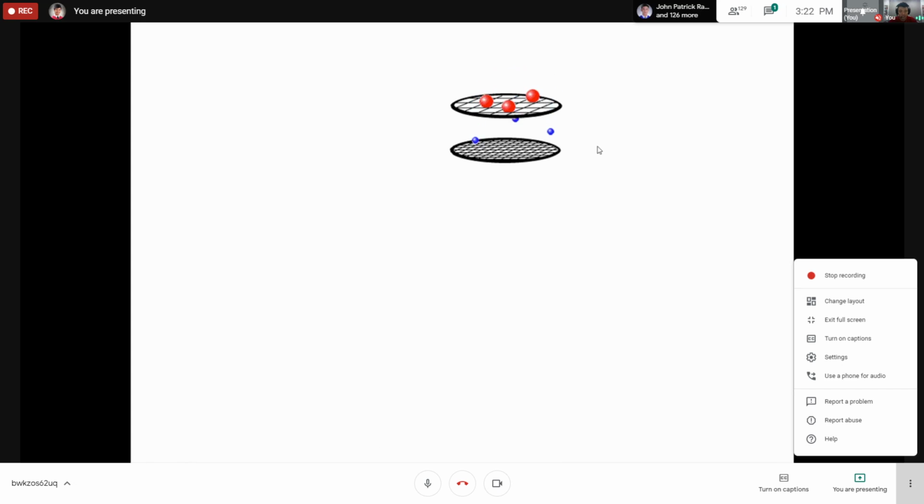So usually in your sieve analysis, once you place it in the sieve shaker, it shakes. So the bigger particles will remain on the bigger mesh, while the smaller components will continue to pass through the different set of sieves until they can no longer pass through that particular sieve.